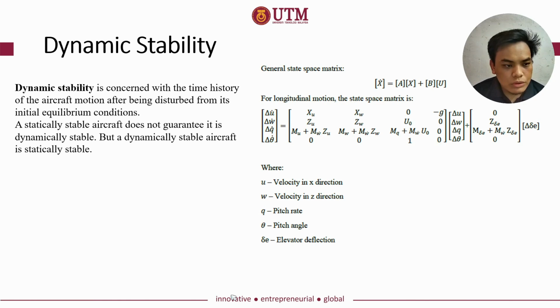Now we move on to dynamic stability. Dynamic stability is concerned with the time history of the aircraft motion after being disturbed from its initial equilibrium condition. A statically stable aircraft does not guarantee it is dynamically stable, but a dynamically stable aircraft is for sure statically stable.